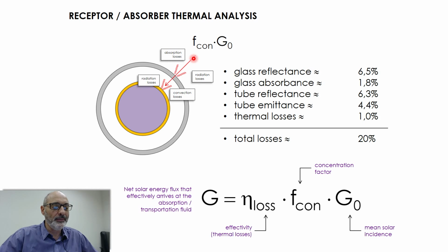But when it enters the vacuum and goes through to the absorber tube, you can also have radiation losses, and also convection losses, because this vacuum is not perfect, and with time the system ages and you start having some air leaking into this region. So you may have convection losses and all kinds of losses actually.